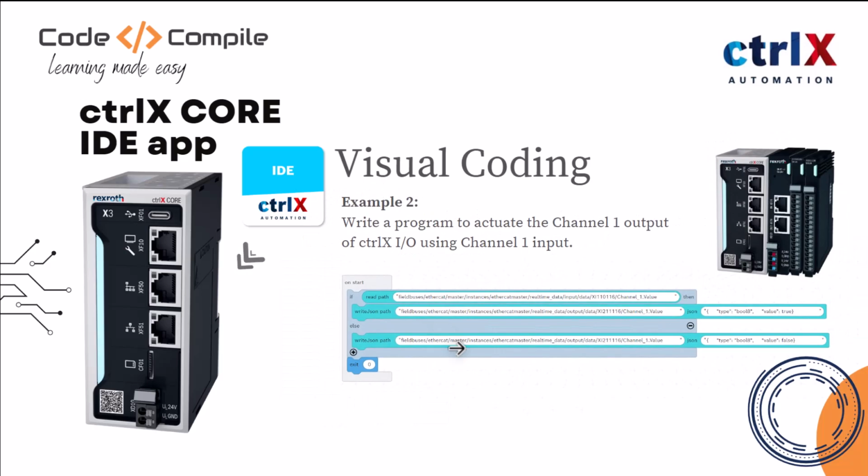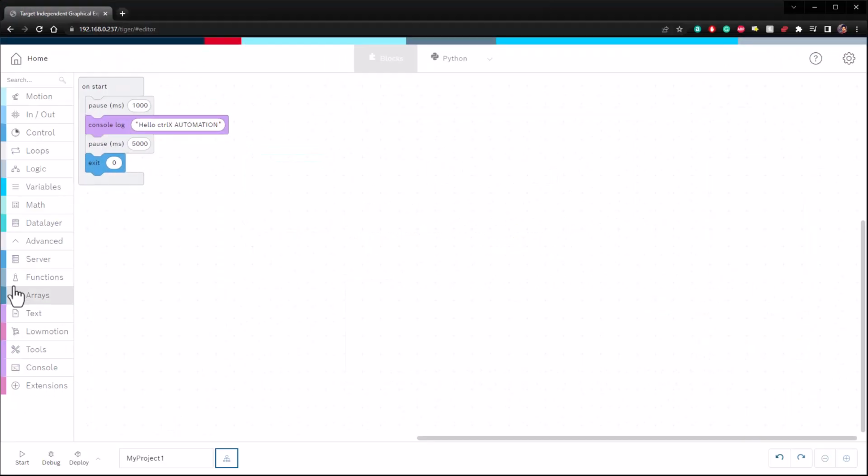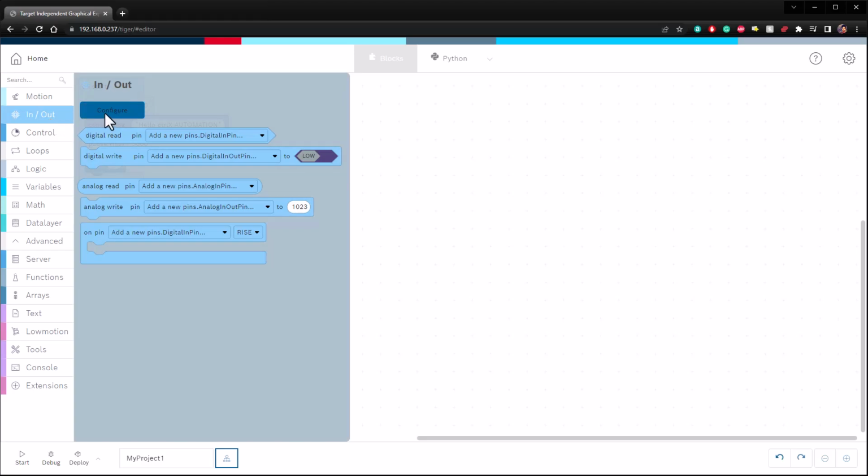In the second example, we want to actuate channel 1 output of ctrlX IO using channel 1 input. So let's see how we can do that using IDE app. I will go back to my ctrlX Core, and here I'll go to in-out. In in-out, I will first define my IOs. In this case, just click on that and go to configure.